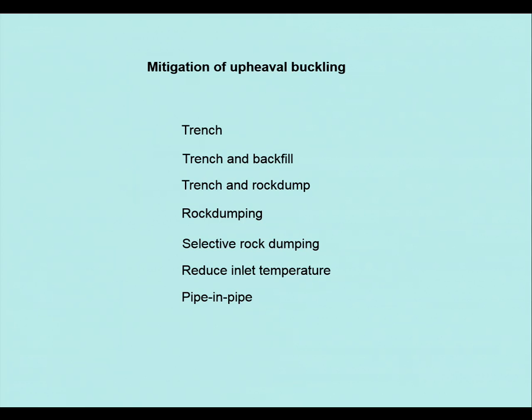Sorry, some questions. Rock dumping, what sort of rock are we talking about? How big? Do they have an effect on the concrete coating? Well, they're normally big stones. There's half of Norway in the North Sea on rock. And sometimes they put smaller rock on first, because when they first did them, they knocked these big rocks on and they just damaged the pipe.